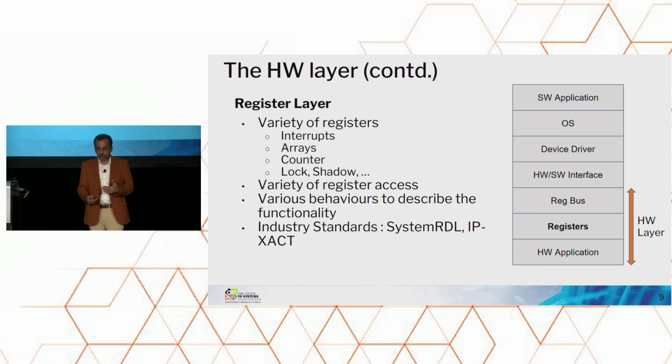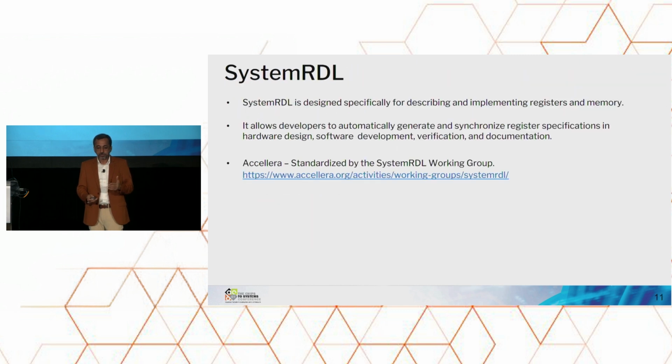The idea is to capture, in a declarative manner, the interface that the software sees of the hardware. People have their own implementations, or you can get commercial solutions where you can take these System RDL descriptions and generate RTL from them.